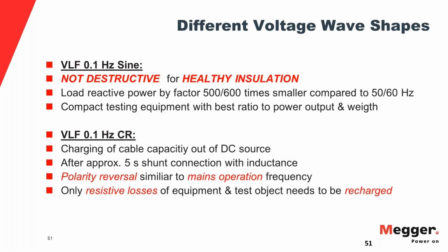The problem really is that originally PD testing was not done with VLF, and then the market demanded it or asked the manufacturers, and then as a second development, the VLF waveforms came into play. And there's two. Again, I want to call back to the webinar in December. Remember, the first one, the original, was the cosine rectangular, invented by Eckhard Lehfeld at HDW in Kiel. And that was the cosine rectangular VLF.